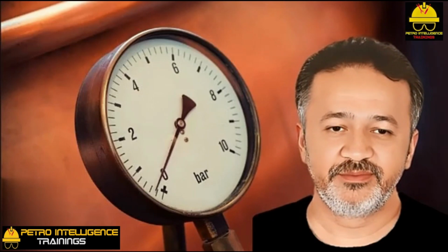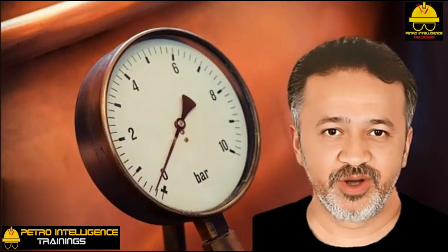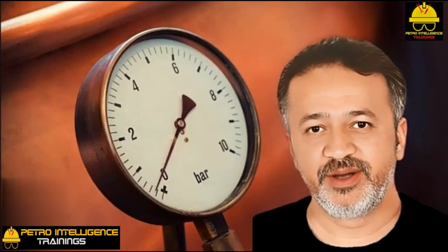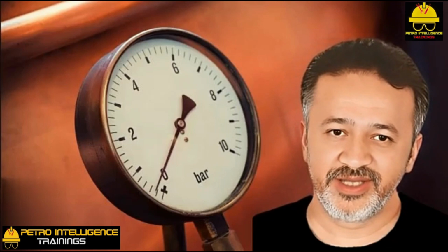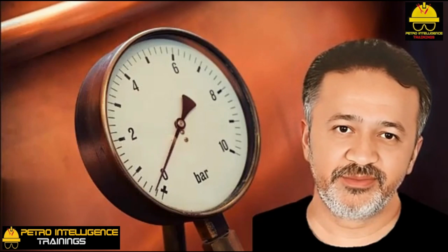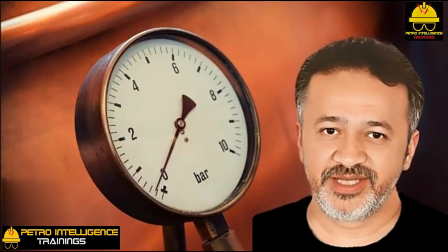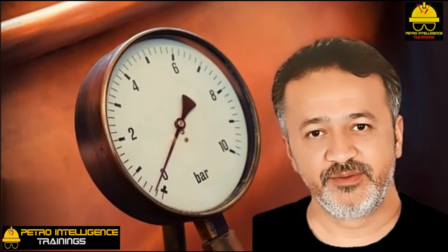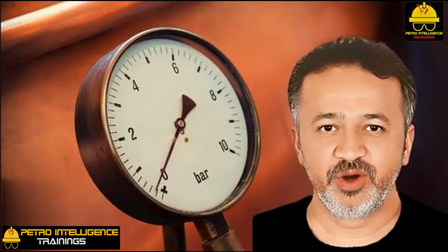Short thermowells. For a thermocouple to read correctly, it should be fully inserted in a thermowell and the thermowell itself should extend several inches into the process liquid. If the process stream is a vapor, which has poorer heat transfer properties than do liquids, the thermowell, especially if the external insulation is poor, should extend more than 6 inches into the process flow. To check the length of the thermowell, unscrew the thermocouple assembly and pull it out, then simply measure the length of the thermocouple. This is also a good opportunity to verify the control room reading with a portable temperature probe or a glass thermometer inserted in the thermowell.